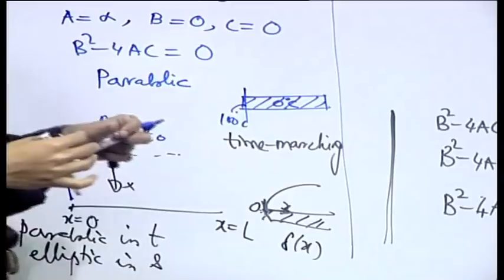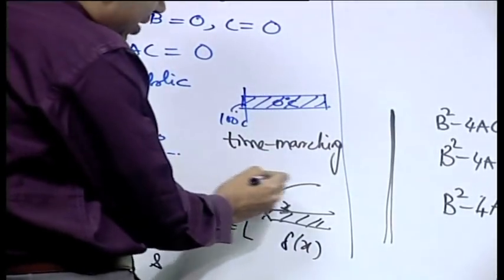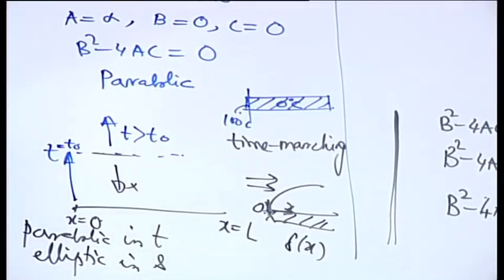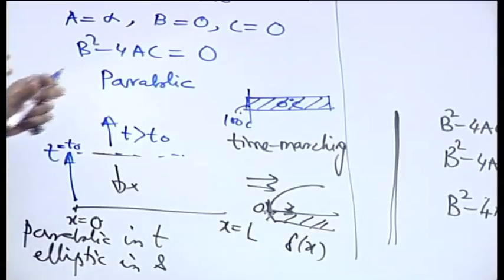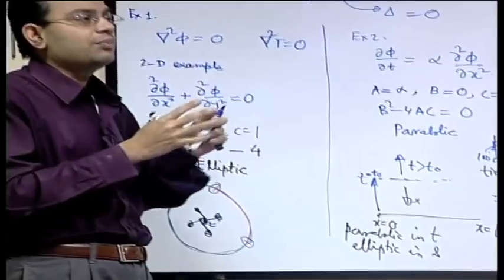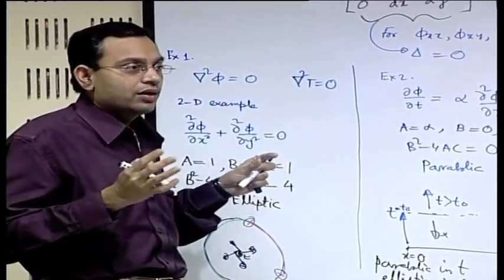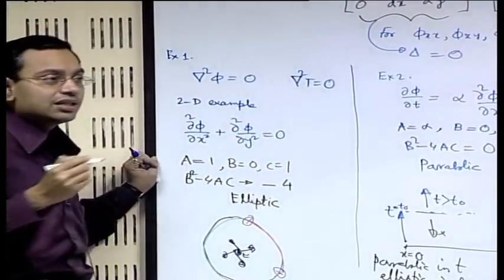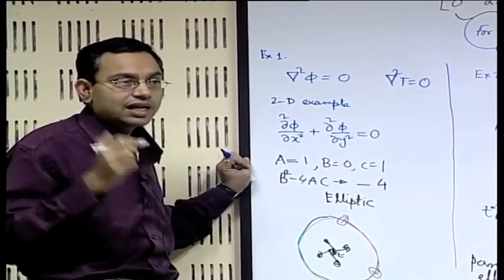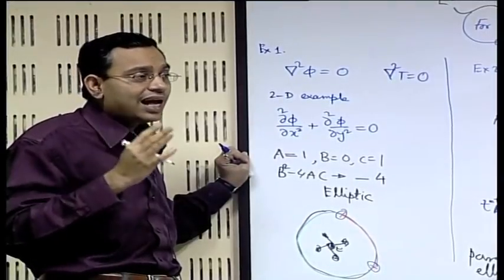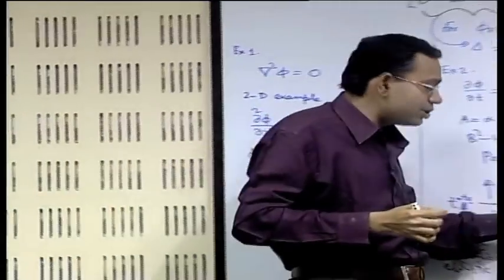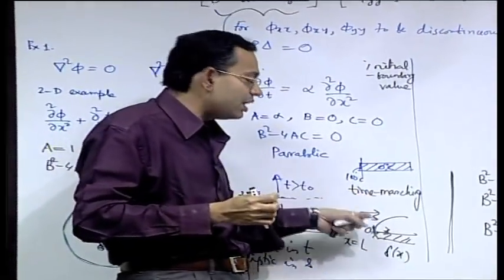And why is that possible? It is possible because this boundary layer theory you are developing for high Reynolds number. So, inertia force is very strong. So, essentially what happens, viscous force is a force which tries to propagate its message in all possible directions. So, if you have a momentum disturbance, that momentum disturbance tends to propagate in all possible directions at infinite speed, that is the effect of viscous force, whereas inertia force is like a unidirectional effect, because inertia force is very strong for boundary layer types of flows.